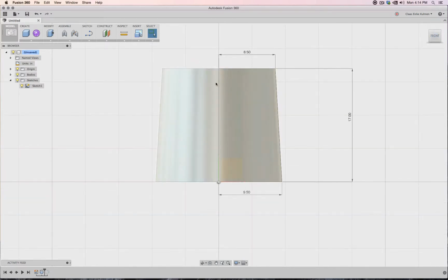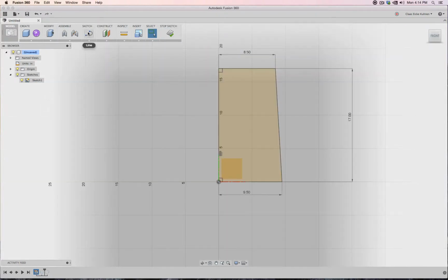I would like to split this solid somewhere around here. So I go to Sketch, Edit, Make a Line. And I'm simply clicking a line, and then you see I drag it to the right till it hits it. You see there's an X, so it intersects.